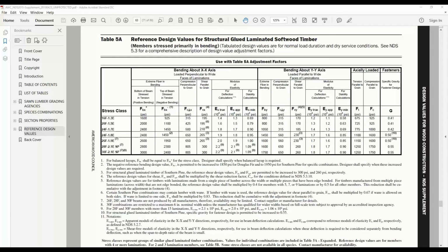The first question, I think this one might be good for Bob. Bob, I know Liz had talked about some of the architectural and industrial classifications of Glulam, the appearance grades. Do those appearance grades have any effect on the structural capacity of the Glulam? No, they really don't. You can specify any of those appearance grades, and they don't really affect your structural calculations or capacities. They're really just not part of the equation.